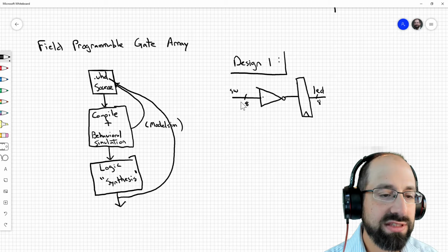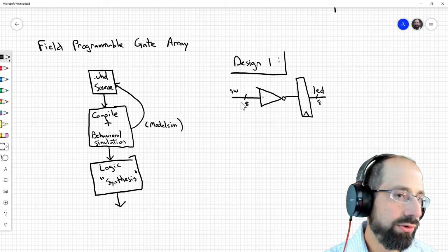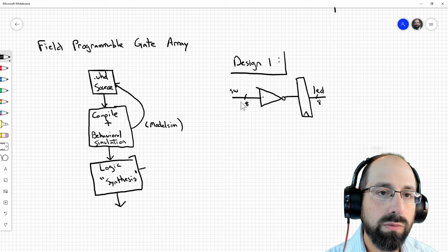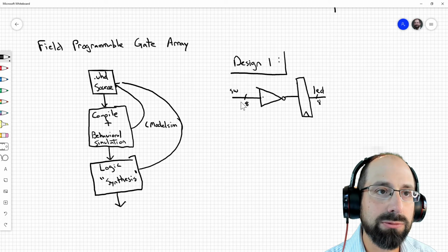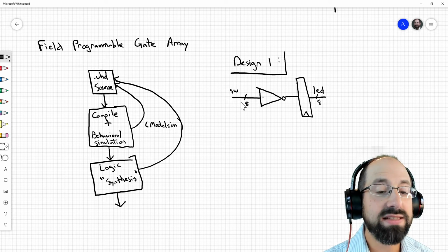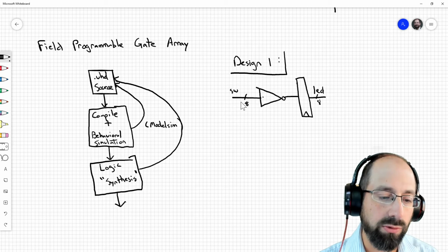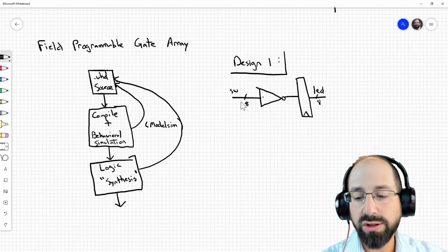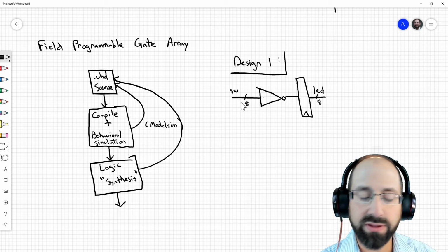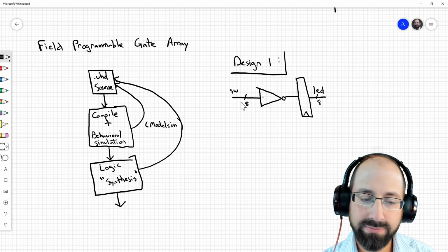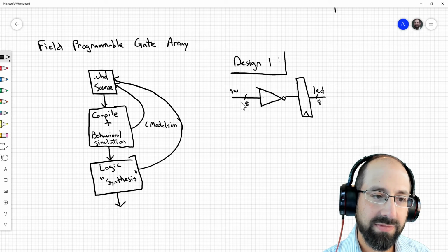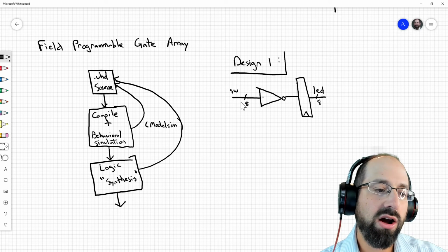And that's a new step for us, right? With regards to ModelSim, we were done, right? We get it to work in simulation, we're done. And now, if we're attempting to map it to actual hardware, the synthesis engine could tell us certain things about our design. It could fail. It could come out with an error, even if all your syntax is perfectly correct. You may have something that's not hardware friendly.